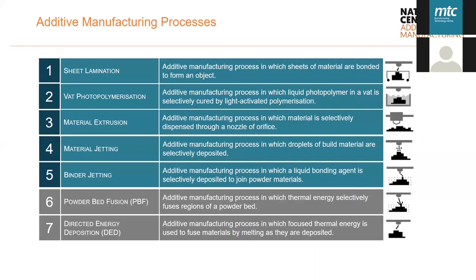Okay, and another one that's come in is, can we print composite materials? And is there an AM method of doing this? Yes, so in terms of composite materials, the sheet lamination process has a composite variant which is in its infancy, only established recently. So I know that there is a process to create composites using sheet lamination. Also material extrusion. Off the top of my head, Markforged manufacture polymer composite components.